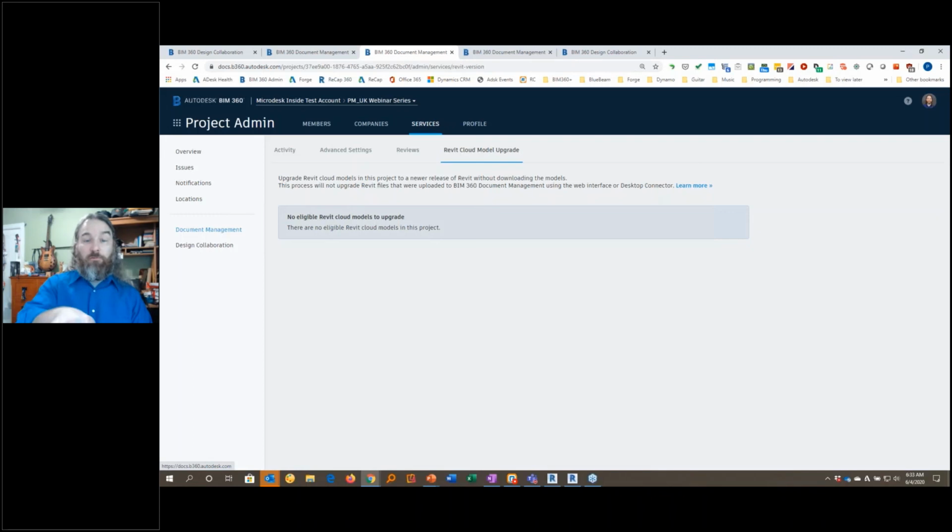So I go through here and I run the test. If there's any problems, it'll let me know what those problems are so I can deal with them ahead of time and plan for it. And then I tell it to run it, and it'll upgrade my project from 19 to 20 or 20 to 21. So that way I can easily manage that. If what I'm doing though is uploading a model, just dragging and dropping it to the cloud, you can have multiple versions of Revit. But when you're doing cloud work sharing, they do have to be the same release.